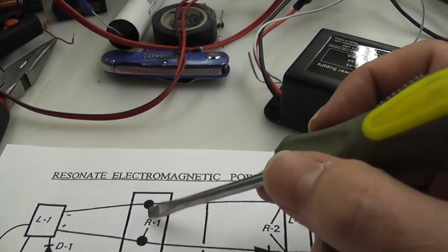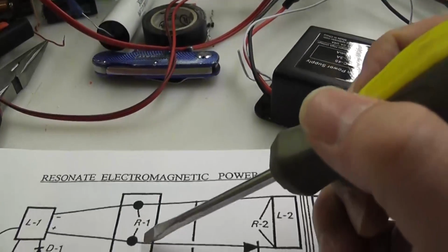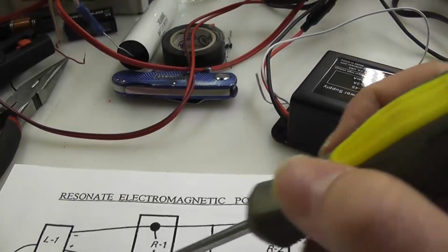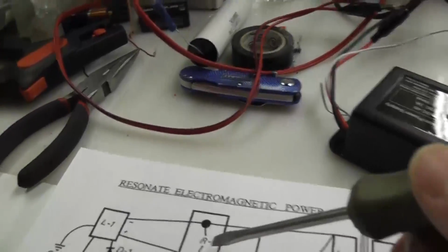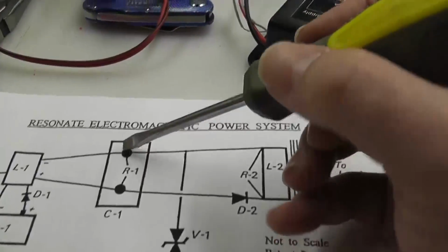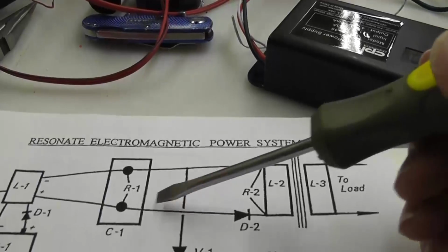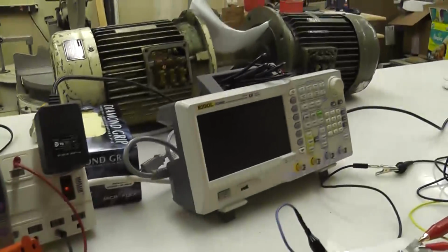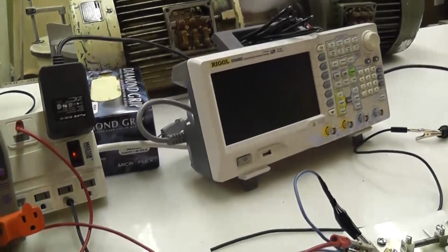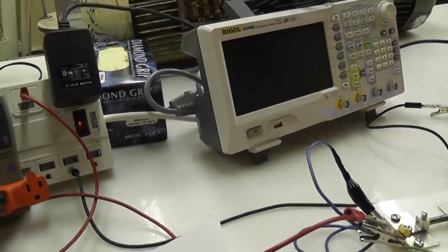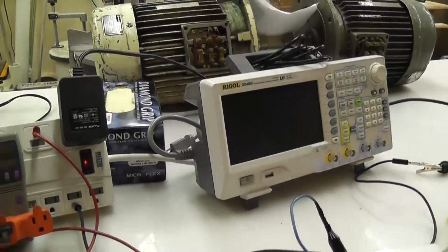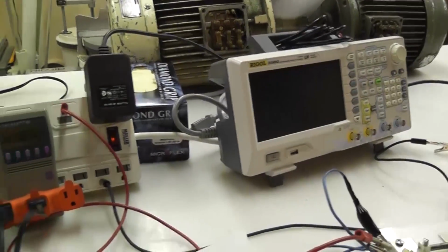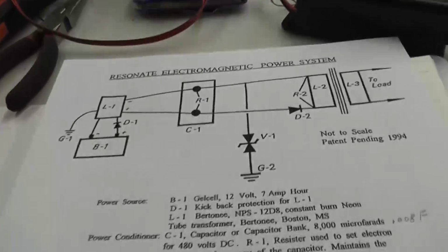So it's going to be very small. And remember, the capacitor is a short to AC, and this is AC. And I know this not only because I'm an engineer and I've done all this before, but because I can hook it up to that frequency generator and simulate this circuit at a smaller voltage, and that thing won't shut off. It'll allow me to do my testing. I can change the voltage and whatever I want to do.